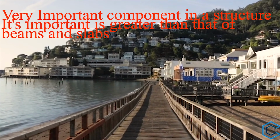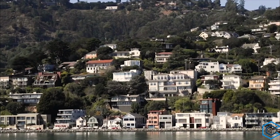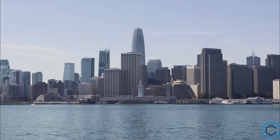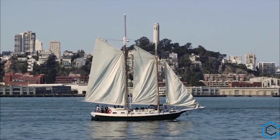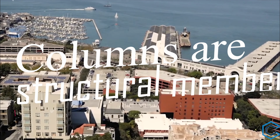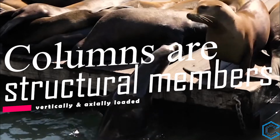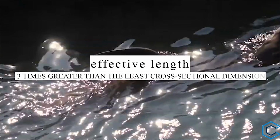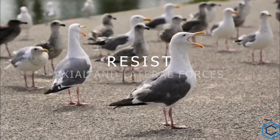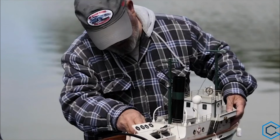Columns are a very important component in a structure. The importance of a column is greater than that of beams and slabs, because if a beam fails, it will be a local failure of one floor, but if a column fails, it can lead to the collapse of the complete structure. So, technically, columns are a structural member which is vertically and axially loaded and subjected to compressive forces, and having its effective length 3 times greater than its least cross-sectional dimension. In short, columns are designed to resist axial and lateral forces and transfer them safely to the footing in the ground.